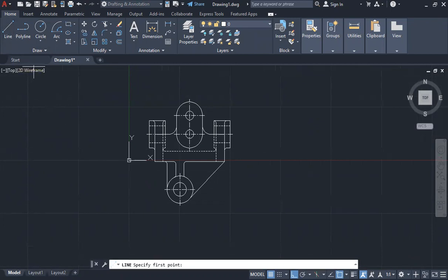First things first, I will establish relationships between certain points. So like my center point here, I'll establish relationships. For this line too, I'll establish a relationship. Like I said, I'll use this drawing to help me draw the next view. So I'll extend my center line somewhere here, any random length. Actually, no, I know that this distance is going to be 50, right? So 50, from that point up, it will be a distance of 16. And then back in line here.